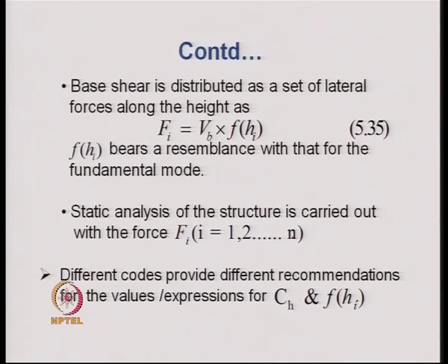Then once we get the base shear, this base shear is distributed as a set of lateral forces along the height of the structure. For obtaining these loads at different floor levels, or along the height of the building, formula 5.35 is used. There we multiply Vb by a function of the height of the floor, and this function of the height of the floor, Fhi, bears a resemblance to that for the fundamental mode of the structure.